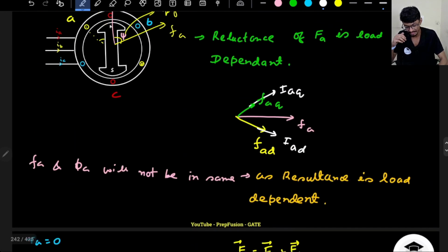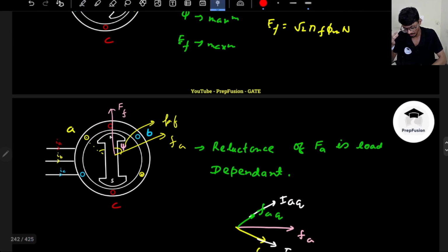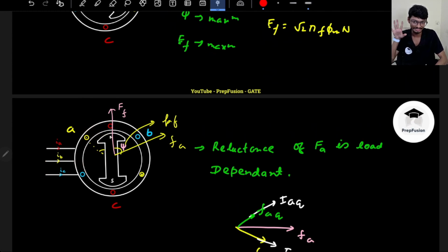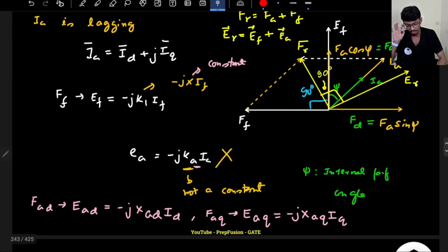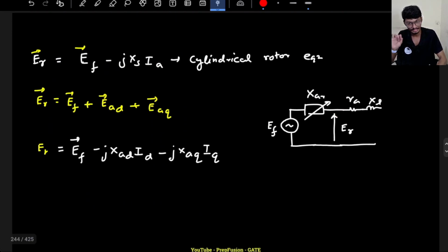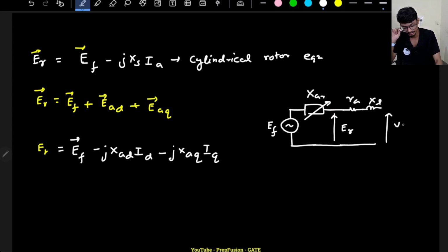No matter what, leakage reactance is how much flux is getting leaked out. So whether I'm following through the direct axis or through the Q axis, leakage reactance will be there in both the paths, both in the direct axis and the quadrature axis, right? So this will automatically get added to both the direct axis reactance and the synchronous reactance, because leakage reactance will always be there, and here this is my terminal voltage Vt. Okay, so that part is I hope clear.